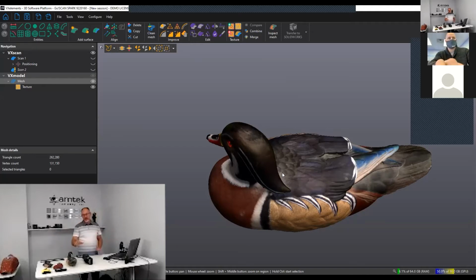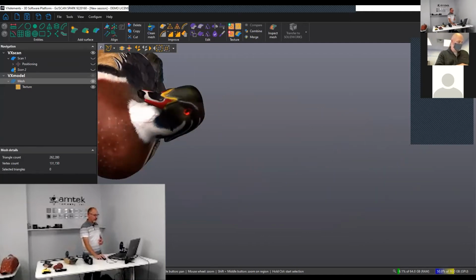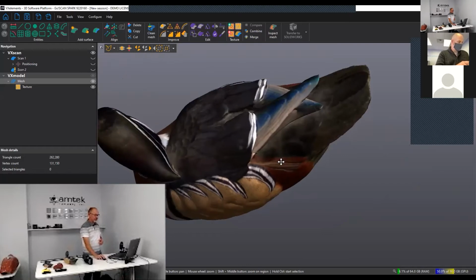This is a little bit different now because in this case we've got full color. So the STL file doesn't transmit the color data. That's not part of the file format. So in this case, we need to use something different. We need to use a file format that will transmit the color. And built into the software here, we have a number of tools that will allow us to do that. And I'll talk about those just briefly. So once I have the model that I'm looking for all cleaned up, holes filled and so forth.